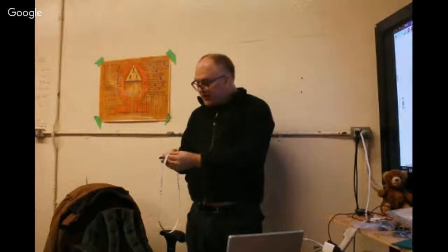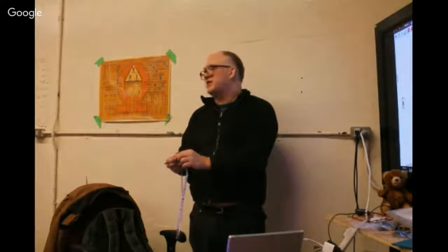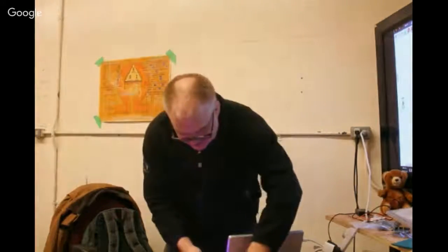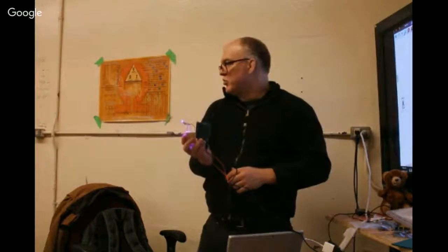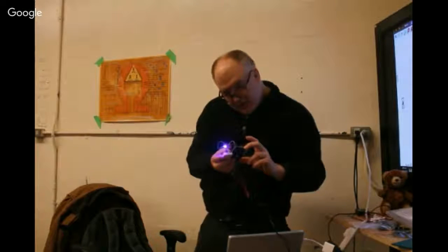We're feeding a signal into the different color channels. The RGB color channels here are taking a signal that controls how bright it is. You can see that my circuit here is going through a fade, from one color to another color, basically varying the brightness of individual colors based on the RGB values. This is using three pins on your Arduino board: pin 3, pin 5, and pin 6. You'll notice there's a little squiggle next to those pins that says PWM. Squint and you can see PWM on there.